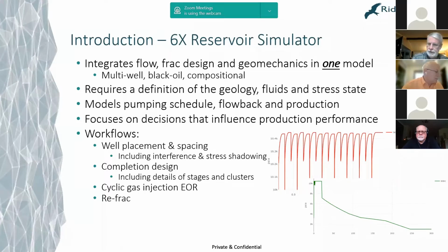It uses the fluid properties, the PVT data for the hydrocarbon fluids, and that can either be a three-phase or two-phase black oil model, or it can be a full equation of state compositional representation of those fluids.